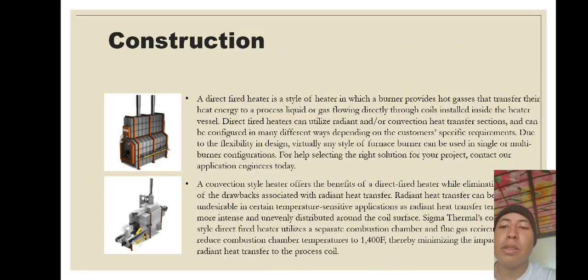A convection style heater offers the benefit of a direct fired heater while eliminating some of the drawbacks associated with radiant heat transfer. Radiant heat transfer can be undesirable in certain temperature-sensitive applications, as radiant heat transfer tends to be more intense and unevenly distributed around the coil surface.